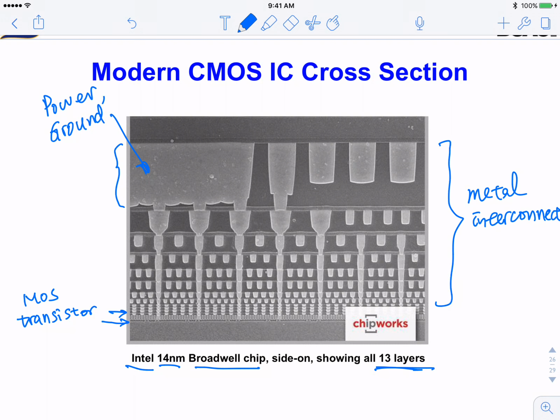You need really low resistance, and conductivity is better if you make them thicker, they carry more current. Towards the bottom here, they are contacting individual transistors. So each transistor actually consumes a tiny amount of current, and the metal can be skinny here. And you need to be the same size as the transistor in order to wire individual transistors. Okay.